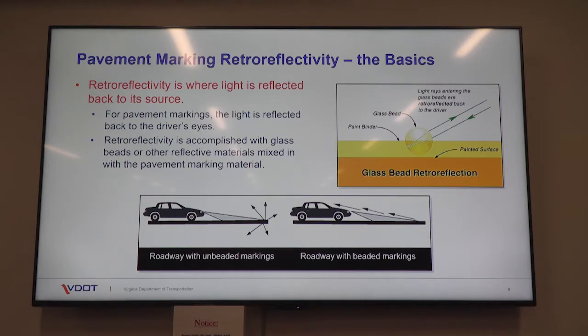So you can see the diagrams here are just simple to demonstrate the difference between reflectivity and retroreflectivity and the importance of the positioning of the headlamps and how the light gets back to you. Federal Highway has a lot of information on this subject. There are different methods of testing for retroreflectivity that the Federal Highway Administration allows. Also, something to note is that the MUTCD, the 2009 version, you may recall, had retroreflective criteria for bringing all signs up to standard, right?